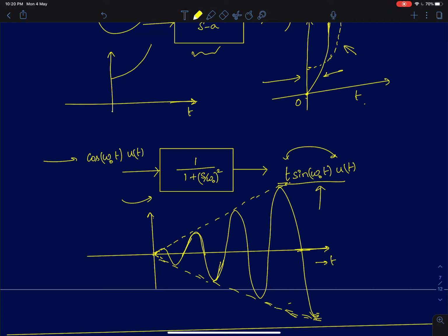You can derive it, because it's a very simple system with just one set of imaginary, complex conjugate poles. But if the system had many more poles besides this one complex pair, and all those poles are on the left of the s plane, then in the steady state the expression will just reduce to this. That's the whole purpose of this analysis.